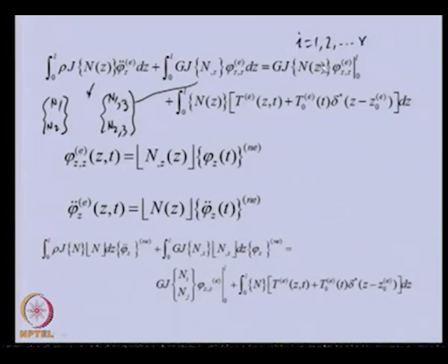And here this is the other term which we got after integration by parts, an additional term, and these are the external torque terms, the distributed torque and the concentrated torque. So, this is the term which we got after integration by parts. This limit shows that particular term. Here also we have put all those Ni in a vector form, so that we can represent this in a more compact form.